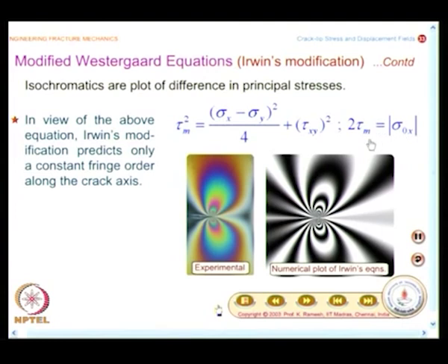In the case of Westergaard solution, the maximum shear stress was 0. Now, it is a constant value. In an experiment involving longer cracks, we saw that this is varying, but for the time being you should be happy when the crack is shorter. Now, we have captured a solution which has a second term which is known as sigma naught x in experimental mechanics literature.